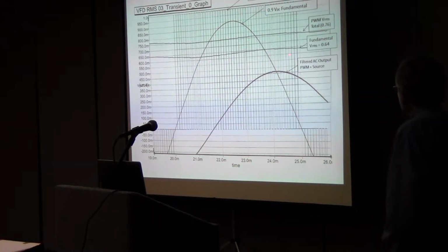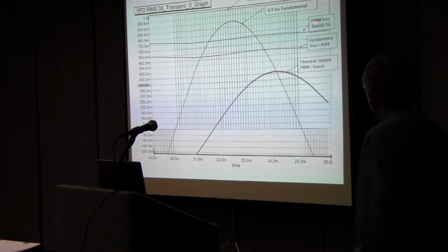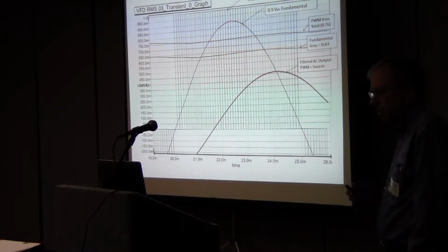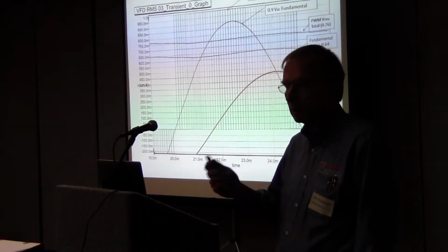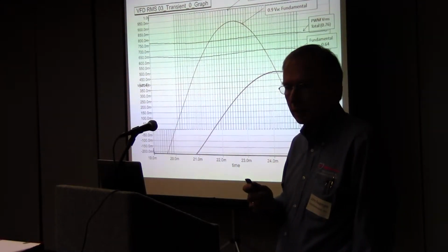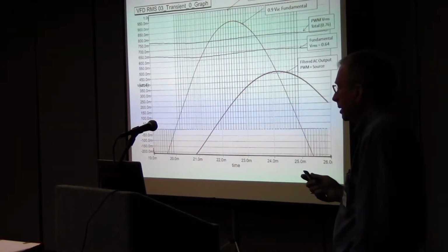These lines represent what you would get if you measured the RMS of this. So for this signal here, we have 0.76 volts RMS, but in fact, you probably only wanted to know what the 60 hertz component going to your compressor was, because that's what's going to put energy into the compressor. Or, you know, I keep saying compressors.